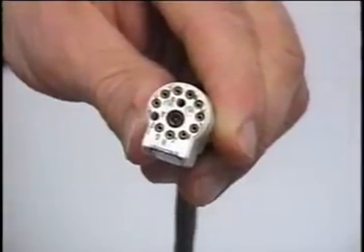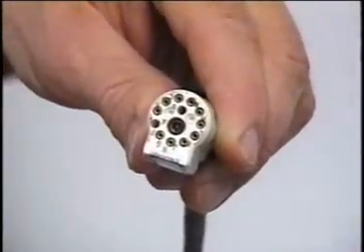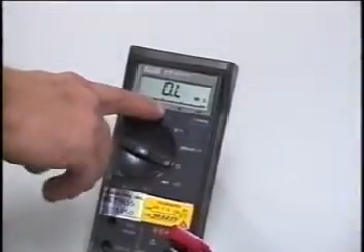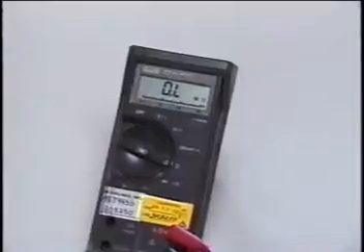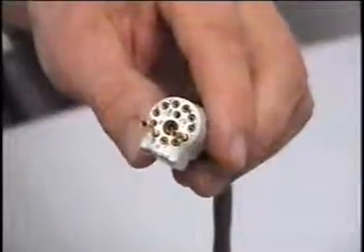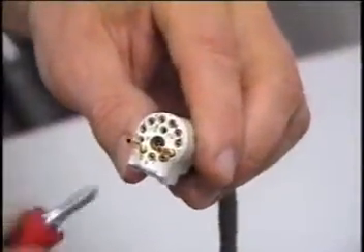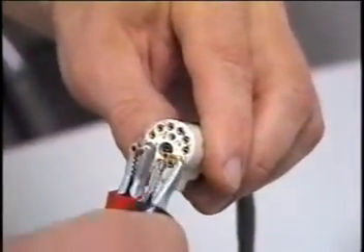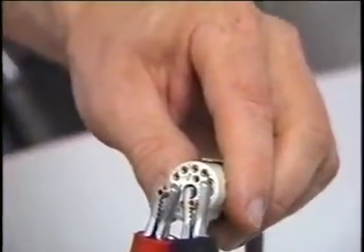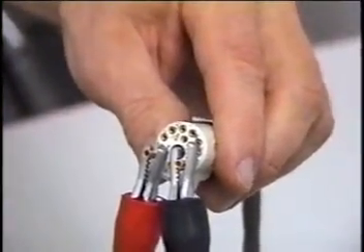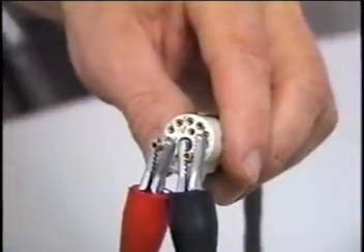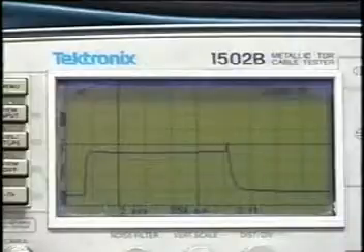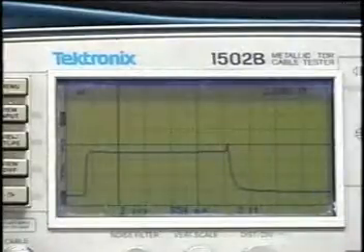The TDR is also useful for troubleshooting wire bundles. When an ohm meter reveals a fault in a wire bundle, the TDR can help you find the location of that fault. Using a wire adapter, connect one terminal to the wire with the fault and the other terminal to a known good wire within the bundle. The distance reading to the fault reflection indicates a logical starting point along the wire bundle to begin your physical search for the fault.